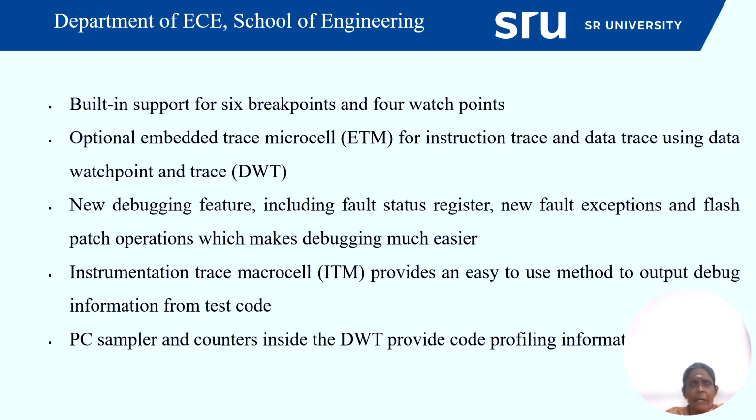Next one, built-in support for 6 breakpoints. Now, what are the breakpoints? The breakpoints will be created in the instruction to check for the error, that is, debugging purpose it is made, and 4 watchpoints. Optional embedded trace macrocell, that is ETM, for instruction trace and data trace using data watchpoint trace, that is DWT. So both work in coordination with one another to debug.